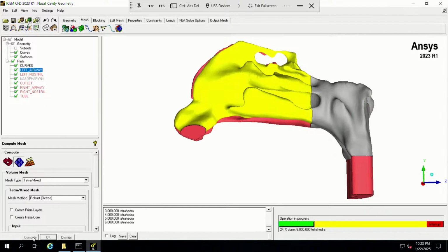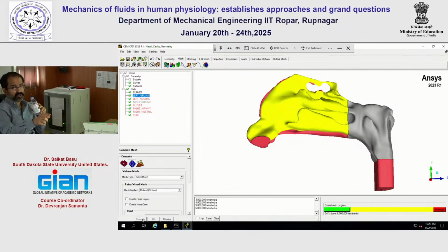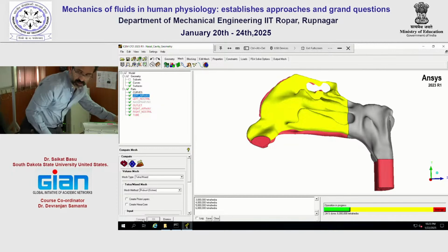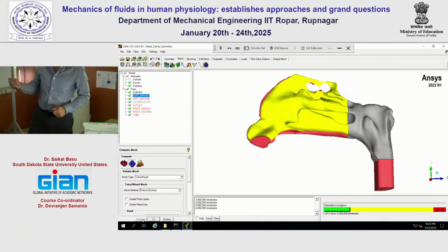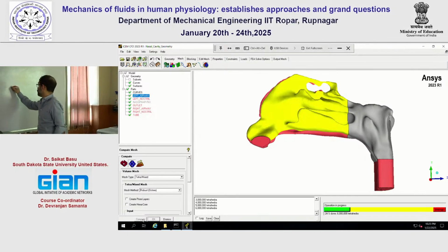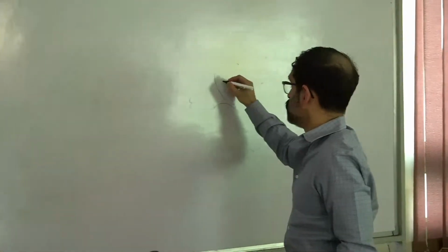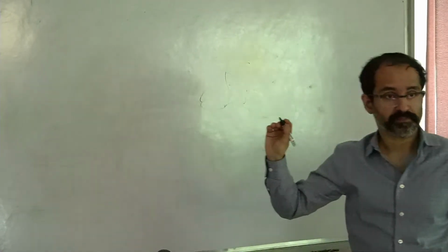No, this is not a solid region. So basically there is a cavity inside. This is not solid. This is just the shell. Yeah, inside is hollow. So you are building the mesh. That is a very good question in the sense that some students do have their confusions with this. For example, here the STL is a shell file. So if you look at the cross section, it is hollow. It is not solid, right?